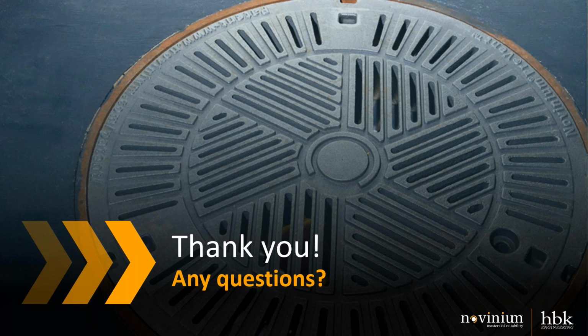So we think our approach handles the first part of that question pretty well, which is when we go into the manholes and we perform our assessment, one of the key activities is mapping the cables and understanding the duct occupancy. So if we understand what ducts are occupied by cables or bonding or fiber optics or tracer wire, we can then take those next steps to perform circuit verification, understand what circuits and feeders are moving through those. So now from two ends of that, say the manhole on either end of that duct, we understand what's in it. The next steps we could take could go as far as inducing a tone on either a conductor or a tracer wire that runs there and using RF locating to actually figure out its spatial location.